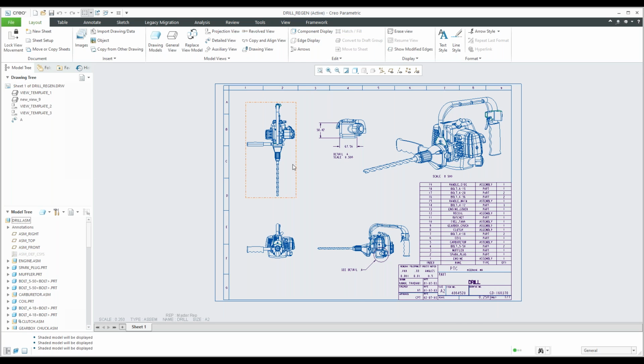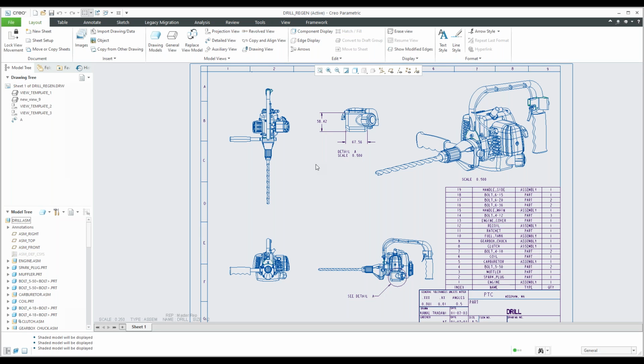We've created this drawing with a certain template. You can see there's a top view, front views, projection views, and a detailed view. If you have detailed views that you want to make part of your template, then your start parts should have that as well. Keep in mind, the templates will use information that's coming from your Creo models.